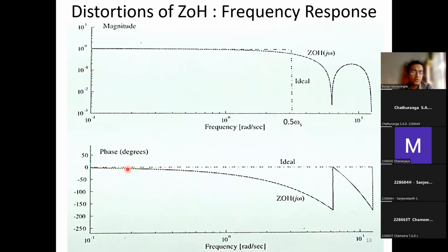You need to have a very high frequency sampler, which is very expensive. So if you design your system originally with 45-degree phase margin, you can safely sacrifice even 15 degrees, right? So you fix the point over here, 15 degrees. Where is 15 degrees? And what is the sampling frequency for that? And that is a kind of safe, low end sampling frequency. All right. Any other questions? And is that clear to you, Dhananjay? Yes, sir. That's clear.